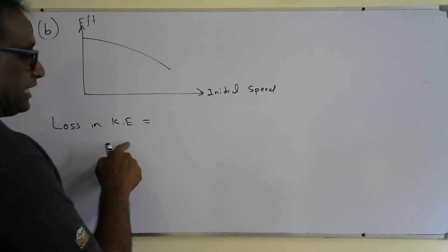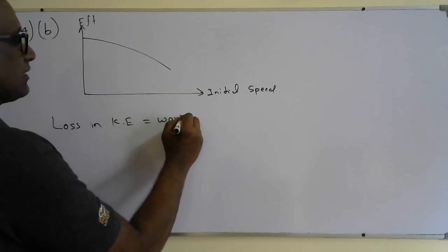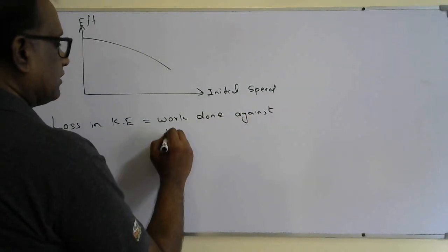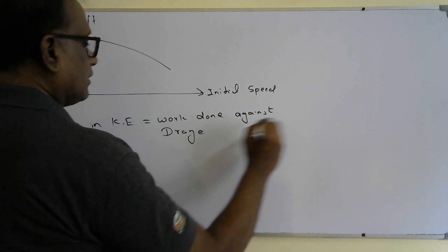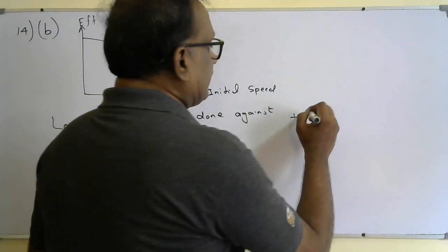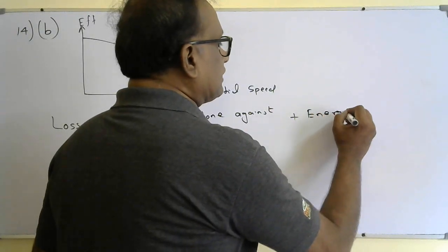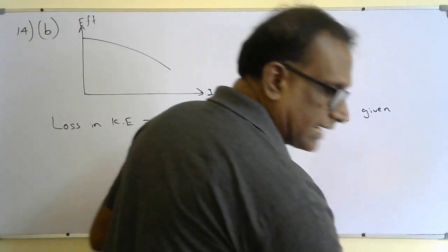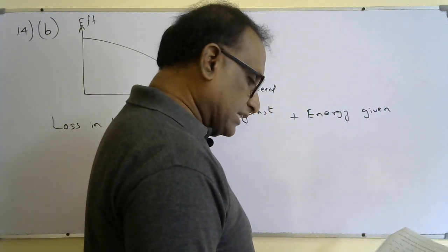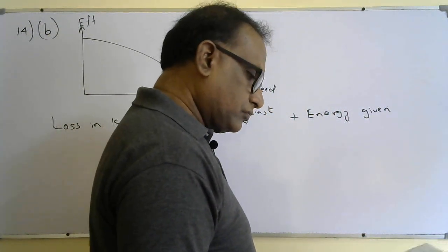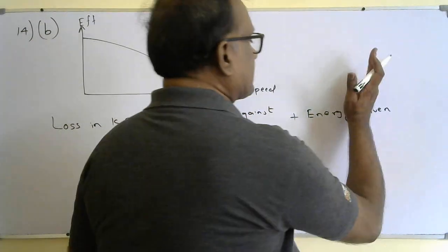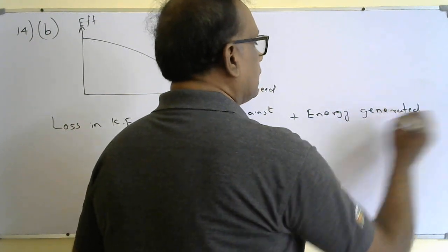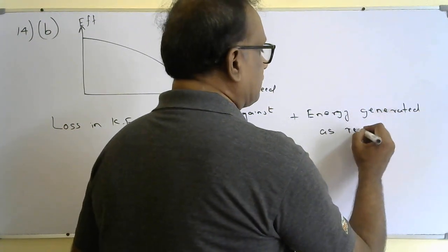So loss in kinetic energy equals work done against drag force plus energy stored in the regenerative system, or energy generated by the regenerative system.